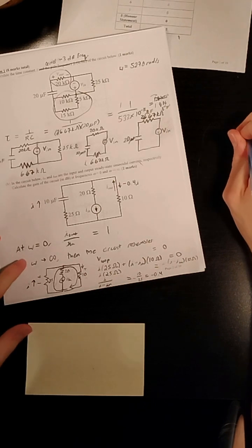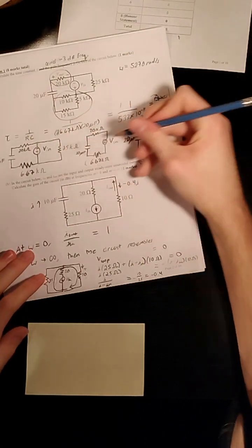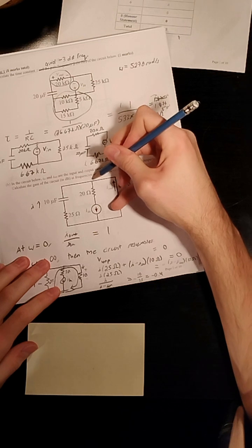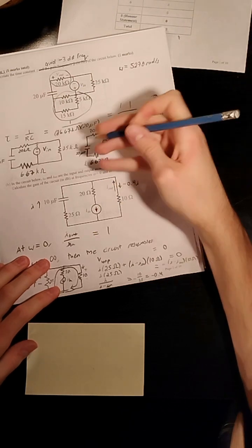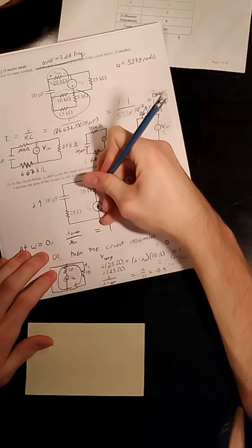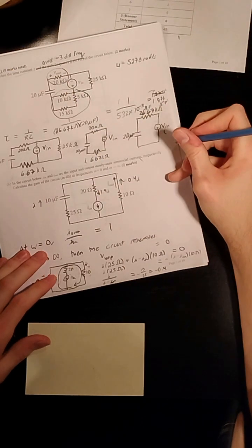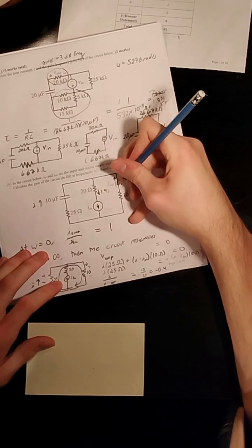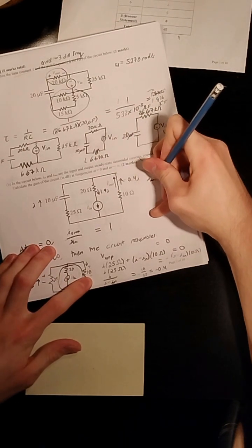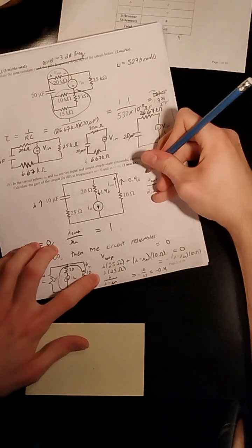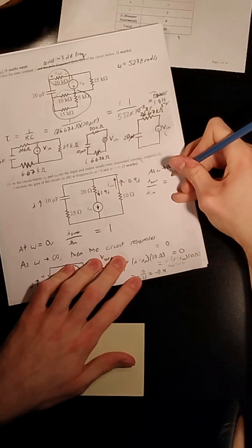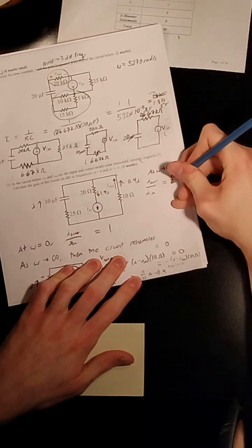Okay. So if you were to do KVL, you would say that I is coming this way, and then after this I get negative 0.4 I. So which means that basically it's 0.4 I going the other way. So this has to be 1.4 I. And then if you wanted to do, so this is I out is 0.4 I, and then I in is 1.4 I. So I out over I in as W approaches infinity is equal to 0.4 over 1.4.